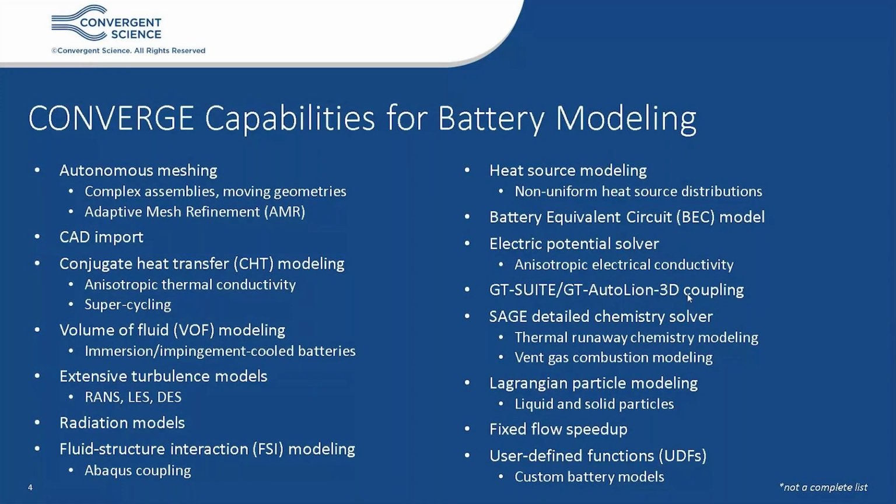Battery simulations within Converge are typically 3D conjugate heat transfer simulations, whereby you model both the fluid and the solid domain in the same simulation, and their temperature solution is coupled at interfaces. For 3D CHT simulations, appropriate solid thermal properties are included.